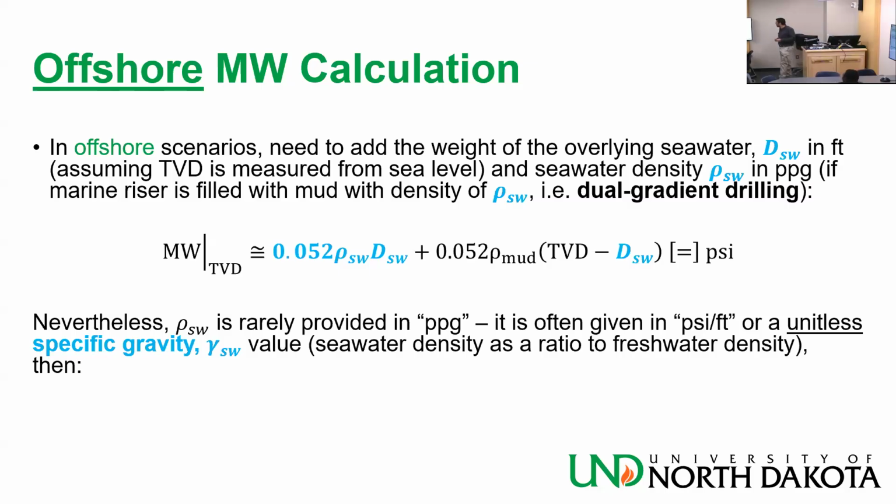You said the TVD there is if you measure it from where? From the surface of the platform. Yeah, you can. There is TVD BRT, small b. That means when you read drilling reports, they have this TVD BRT, below rotary table. Where is your rotary table? It's on the platform. But sometimes you also have TVD SS, subsea. Now it's starting from the sea level.